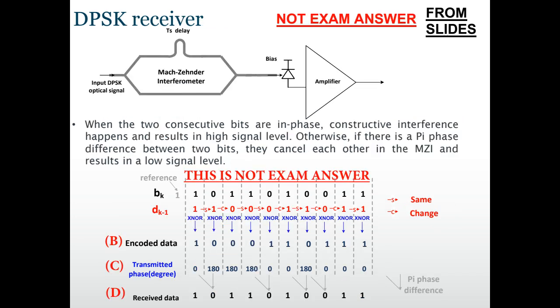Okay, so if I look at DPSK receiver, because we modulate symbol onto the phase change between every 2 consecutive signals, as a receiver, we can just interfere the received signal with its own delayed signal. So when there is an optical phase change, we know the binary bit should be 0. All the rest are 1.